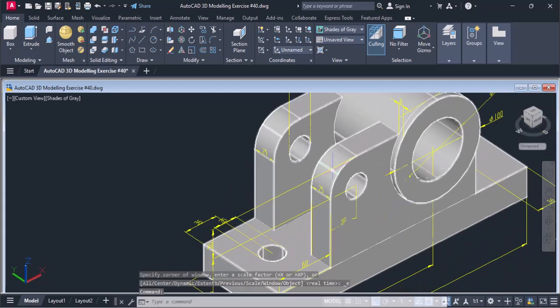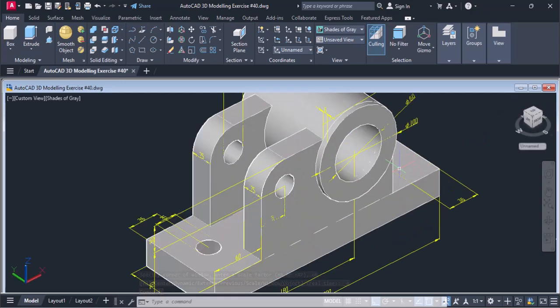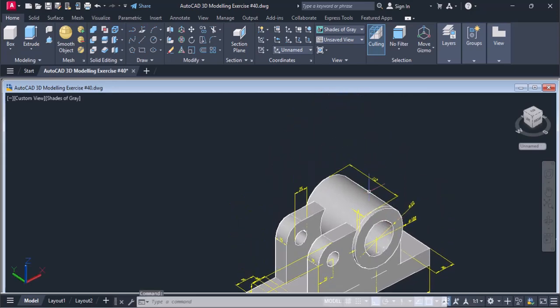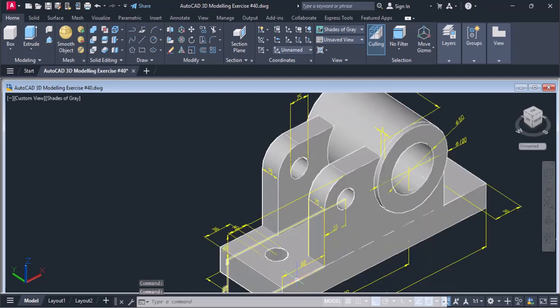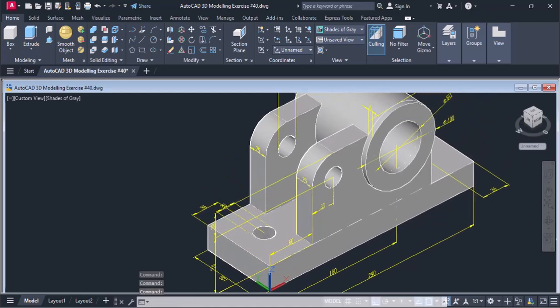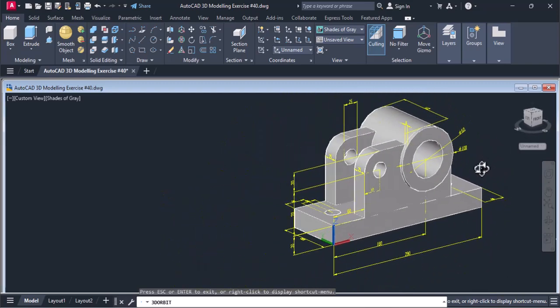Once we have done that, we will go into the 3D isometric view and push pull this circle to a distance of 112 units. Then this entity at a distance of 25 units and the lower rectangle at a distance of 100 units. Then we'll copy this entity to the left. Then we'll draw a circle of 25 dia and also copy it to the other side over here as well, and our geometry would be complete.